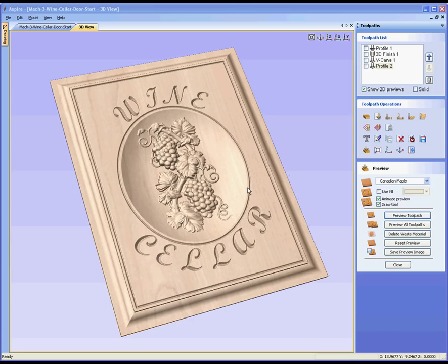The next thing we did is we decided to cut the 3D part of the model. Now the important thing to realise there is we'd deleted effectively all the components except that dished area, but because that was the only area that we were actually applying a 3D toolpath to, it's the only part that needed to exist with regard to actually cutting it.